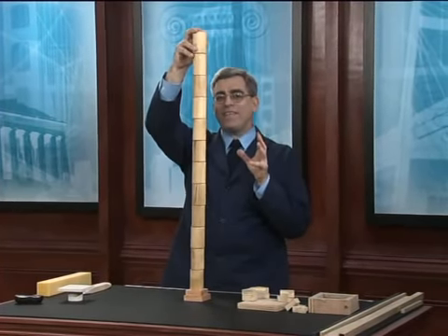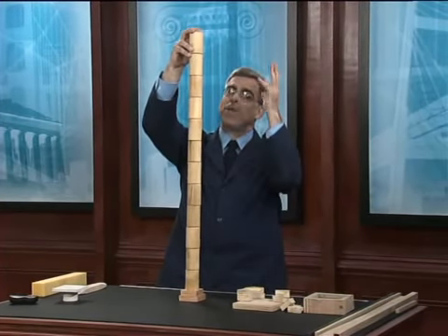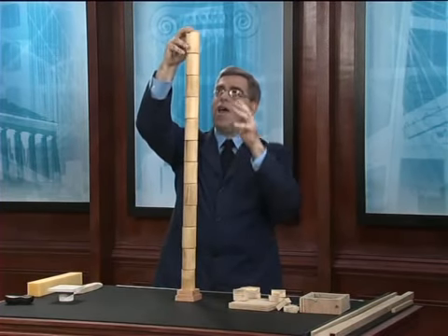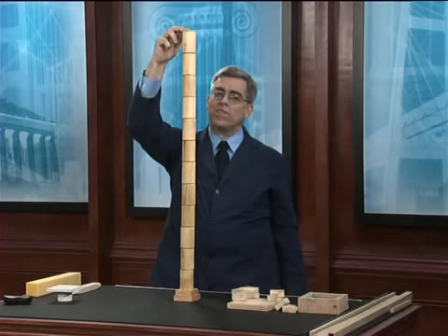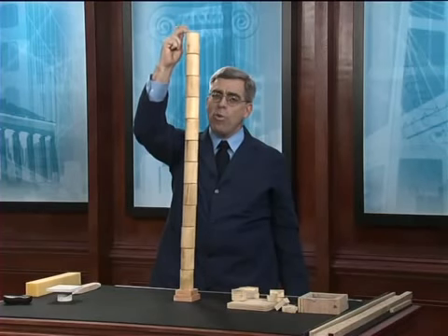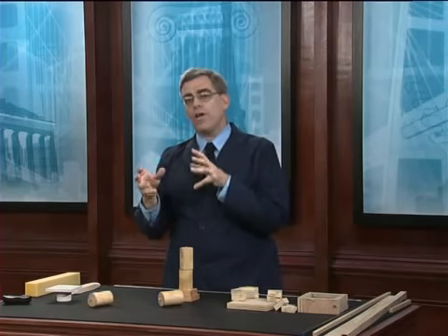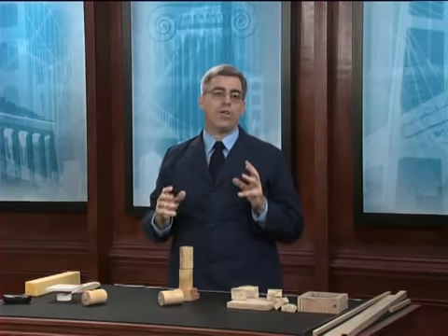And I think you can already see that long before this column gets to be a mile high, something else is going to happen, something bad. As the weight continues to pile up on the top of the column, at some point we're going to start seeing instability occurring in the column rather than a material failure.